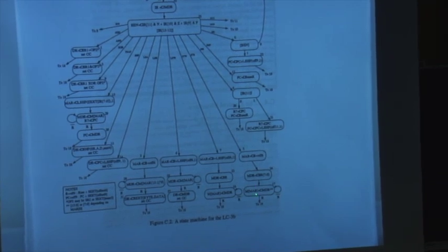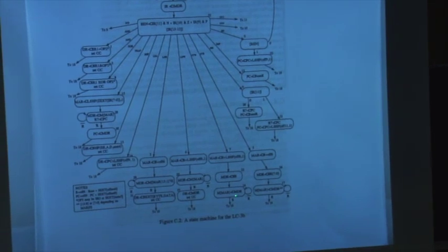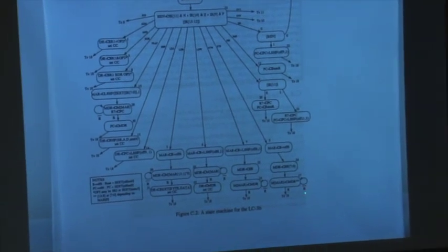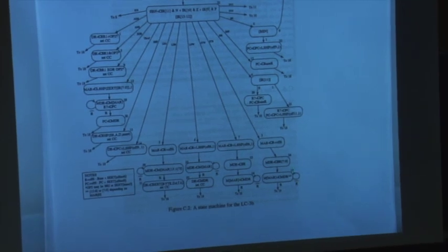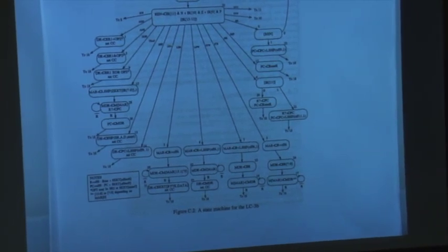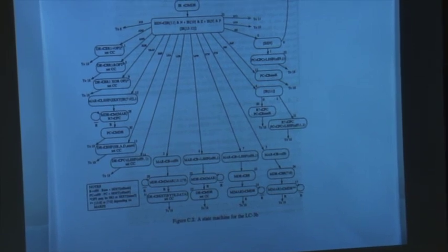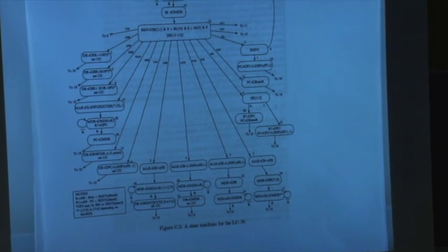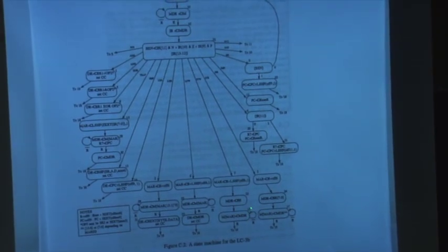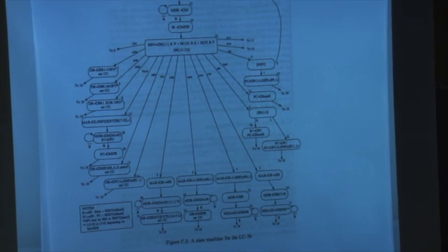Once the store is done, you still want to go back to state 18. But these transitions are actually conditional. Here, you encoded your states such that this is state 16, 17. From both of those states, you want to be able to go back to state 18. But the transition is conditional. It's dependent on this ready bit. Well, state 16, if the ready bit is set, the next state should be 18. How do you ensure that?